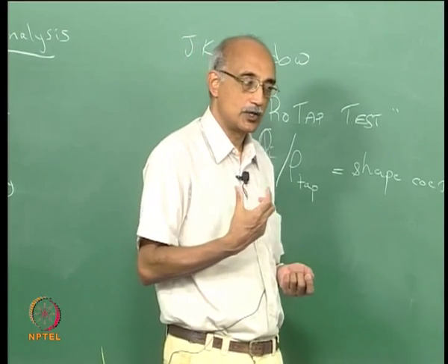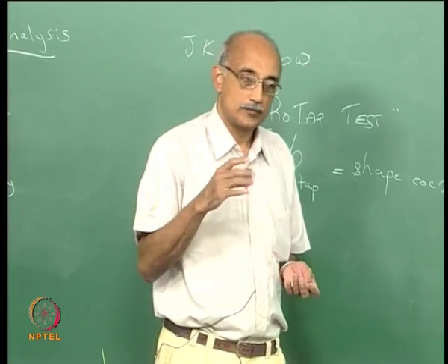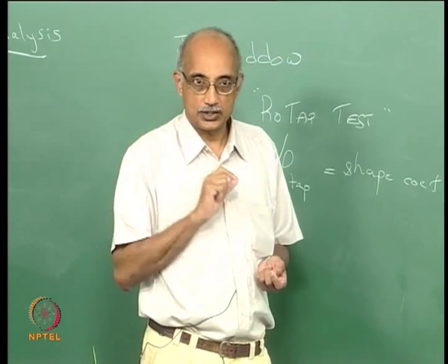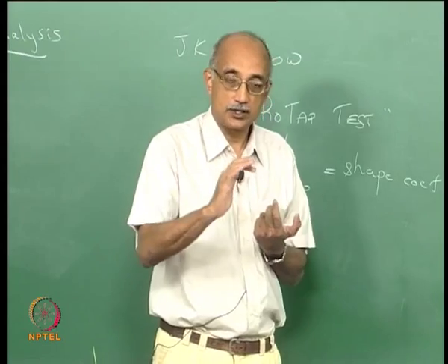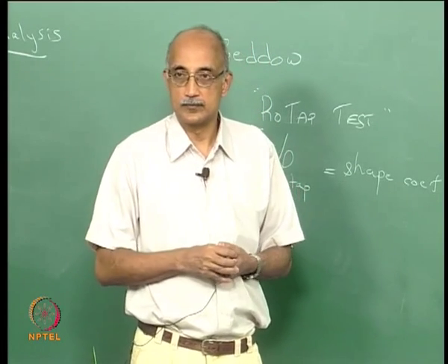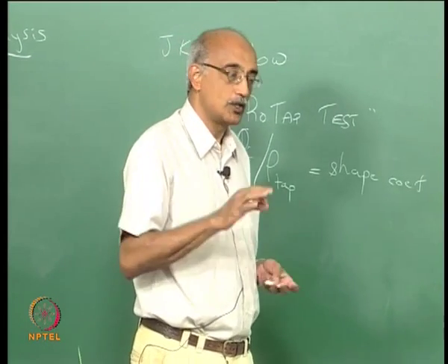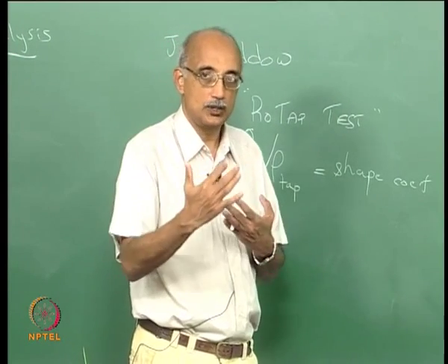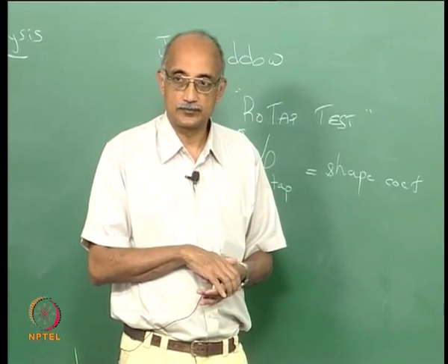In other words, if you are using certain mathematical algorithms to get the best fit of a polynomial to the digitized points that you have obtained, you can actually start deviating further and further from the actual profile by trying to do this curve fit or data fit. So, there is a risk associated with using polynomial fits. The more you try to improve the fit, the more error you may be introducing in terms of the deviation of the shape that is recreated from the shape of the object.